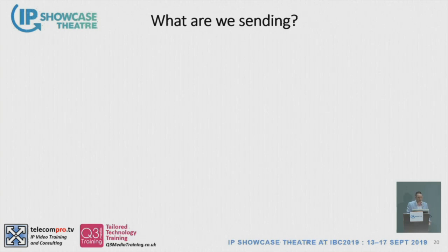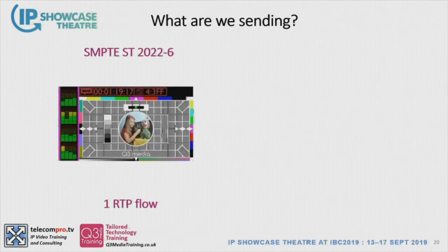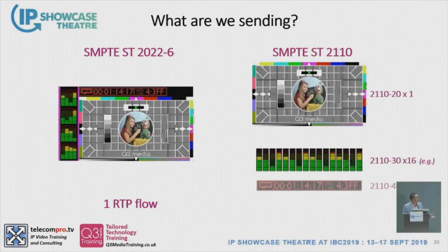So what are we sending? Video. What are we talking about? We're talking about television video here. So video with audio. 2022-6 often gets referred to as SDI over IP. Wes is going to talk a bit more on it in a moment. Simple, one RTP flow over UDP, multicast or unicast. Or 2110, where we're splitting it all up into individual essences.